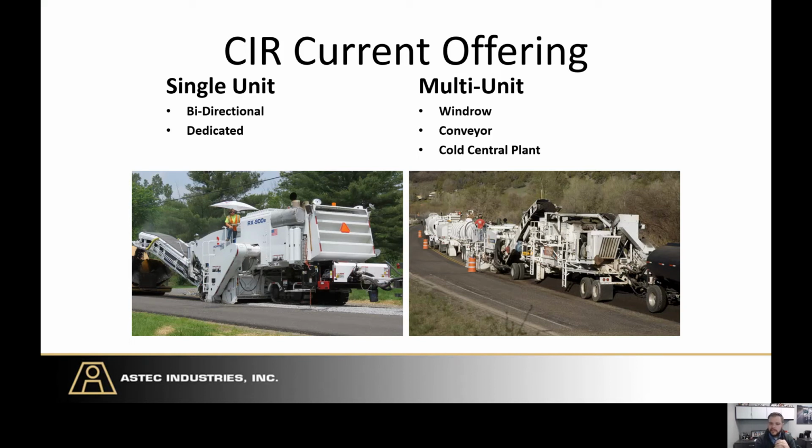So it's based on speed, so we control the sizing with speed. We're down cutting, that also helps us maintain sizing, and we're adjusting the pump based on that forward speed. Then we feed it into a paver. We can also leave it in a windrow. Then on the right, you have the multi-unit. So that's a much more elaborate train, a little bit more logistically challenging, potentially, but more for highway type work.